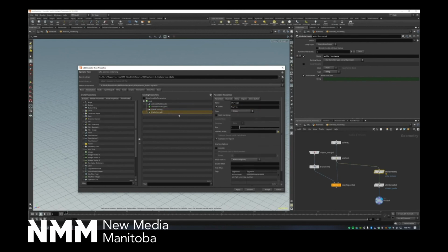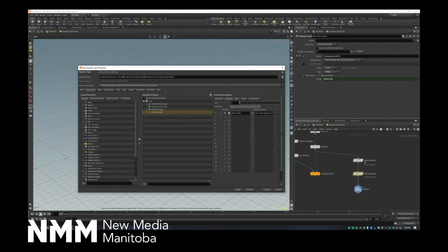And then I've done the same thing with the prefix instance here. I've kept it as a string. You want to keep that as a string. It doesn't need to be an operator or anything like that, because this is just going to be the name of our copied asteroids, and I just labeled it prefix. Another little note is if you go into channels over here, these will normally be blank when you make an attribute, but you can enter a default value. So I've just entered asteroid here. So when we throw this into Houdini, it should by default have asteroid entered in that little UI element.